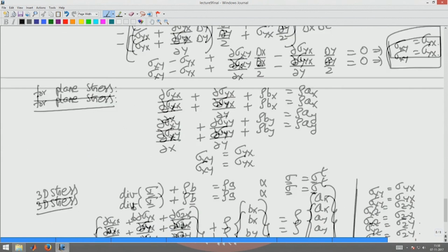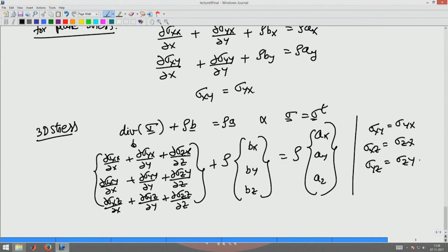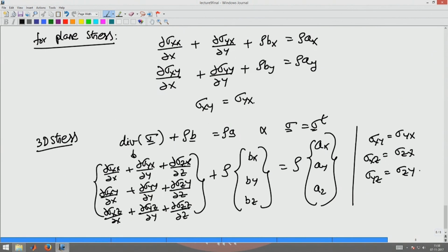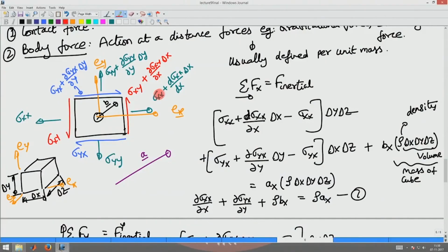derivation here that we saw is not mathematically rigorous, because it looked like there was no restriction on the stress field for us to get the equilibrium equations, but we had tacitly assumed, when we wrote the stress field using a first order Taylor series expansion as given here, that the higher order derivatives have a magnitude which is lesser than the first derivative. This is not always true.